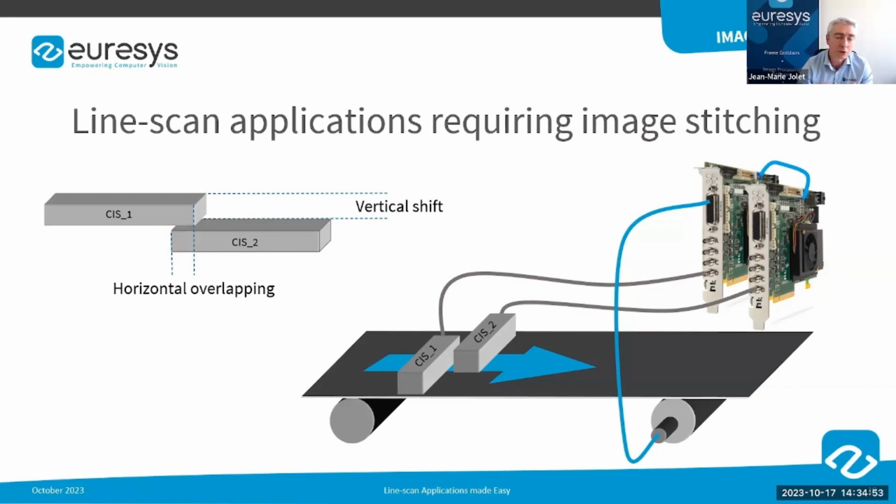It means that it also involves image copy. So Euresys has offered a very neat solution to this problem: the image stitching is actually performed by DMA transfer. Our frame grabbers are DMA agents, which means that they do not need any intervention of the CPU to transfer data into the PC memory.